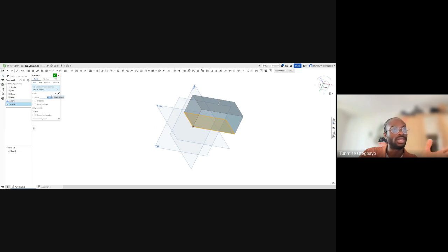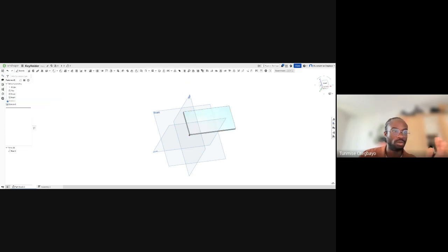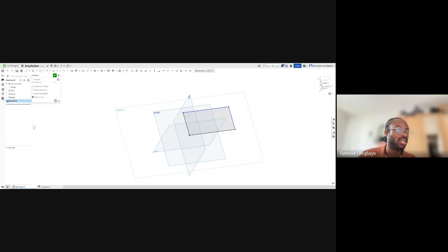And because you're designing things for the real world, you actually want to give it real life dimensions or constraints, because we can't just put anything there. You might want to give it like a 4 or 5 thickness. I think that's fine. But before we start using Extrude, let's go back into our sketch.